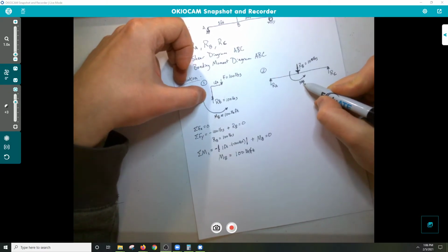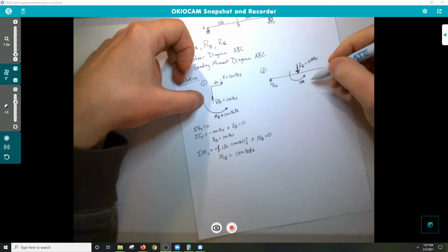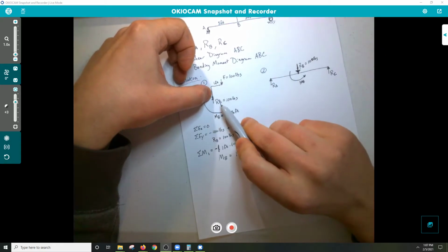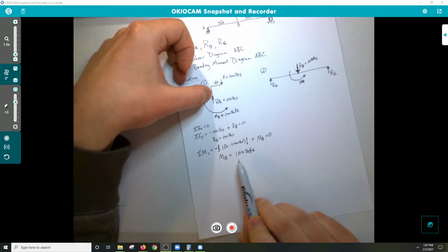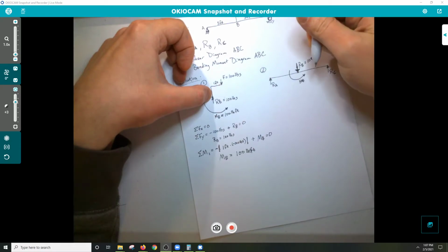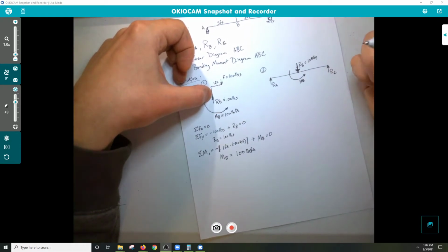And then for moment B, again, equal but opposite, that flips. The neat thing here is, if you always assume positive, when you plug it into the equation and you get a negative, say you have an arrow pointed downward, you know it's supposed to be pointing the other way. That can be kind of confusing.